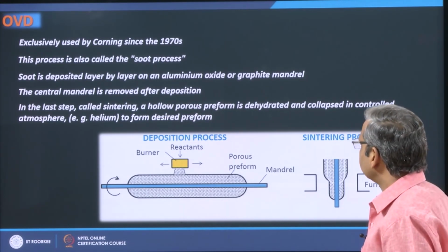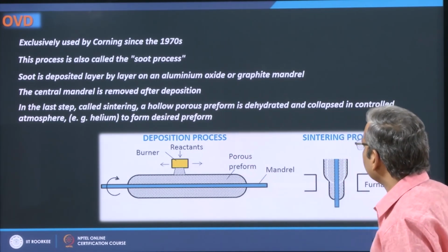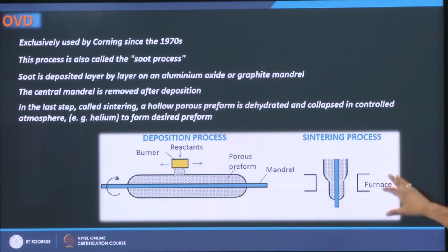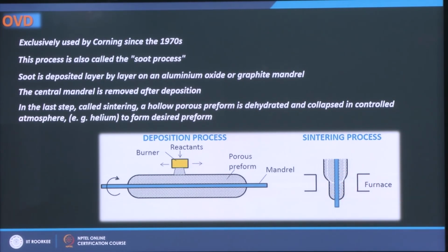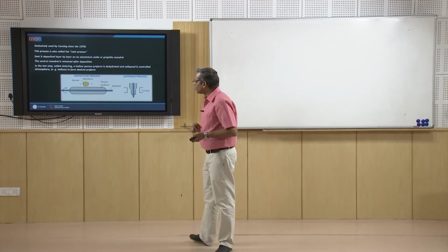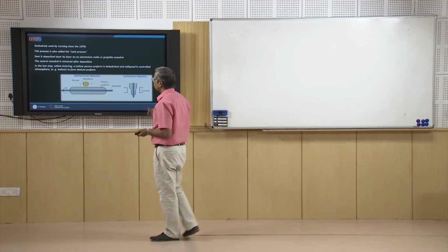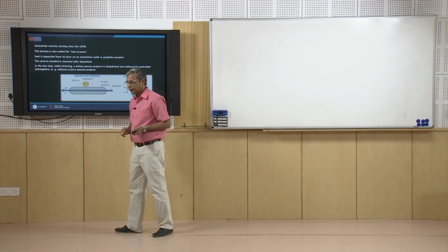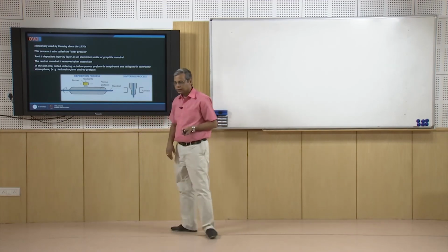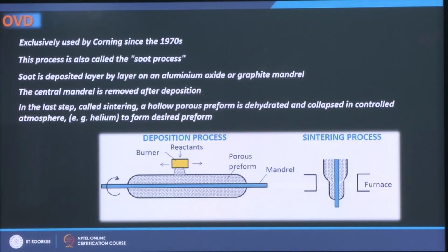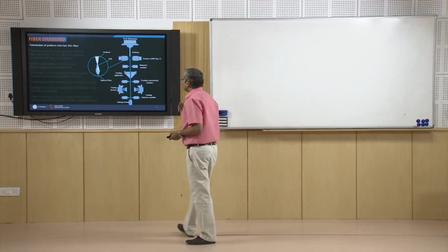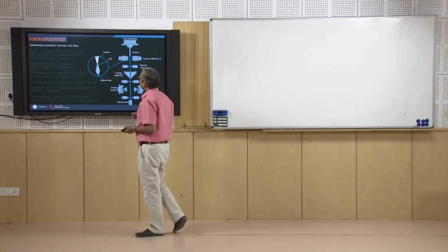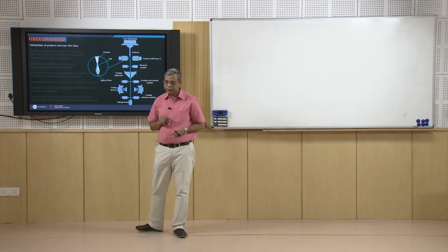This is a typical fiber cable which you put on the seabed. So, it has these optical fibers, then to remove friction between them you put some petroleum jelly, then you house them into a copper or aluminum tube, then you put a water barrier made of aluminum, then you give strength to these fibers by using stranded steel wires.